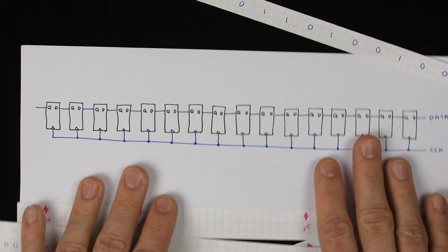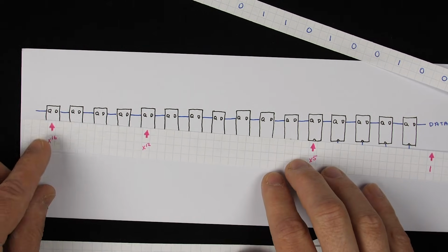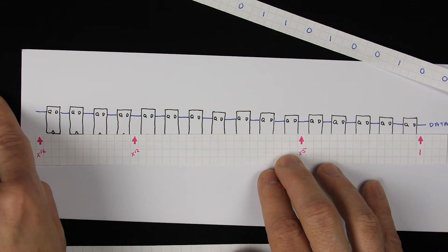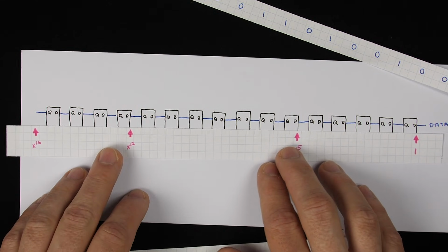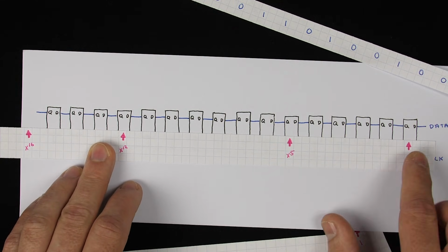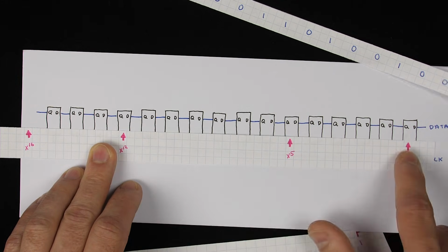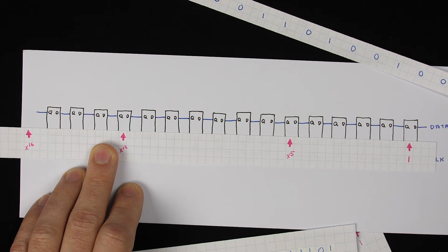Well, in a shift register, if this is our shift register, it's not really that important that we flip that last bit every time because we're basically tossing it out the end of our shift register and we're losing it anyway. So it doesn't really matter that we set it to 0. So you can kind of think of it as the bits we want to flip are the bits that are going into these 3 places. So we really don't need to flip that last bit because we're discarding it anyway.